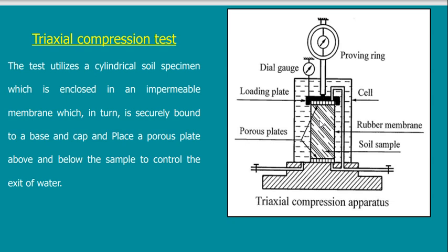The first type of loading is that the sample is surrounded with water, and this water has a tap here. If I close the tap and put water inside, it will compress the sample as it is, and water will not leave. But I also have another tap at the other side. This tap is connected to the sample itself. It means that if I have excess water inside the sample and the water wants to leave, if I open this tap, water will leave.